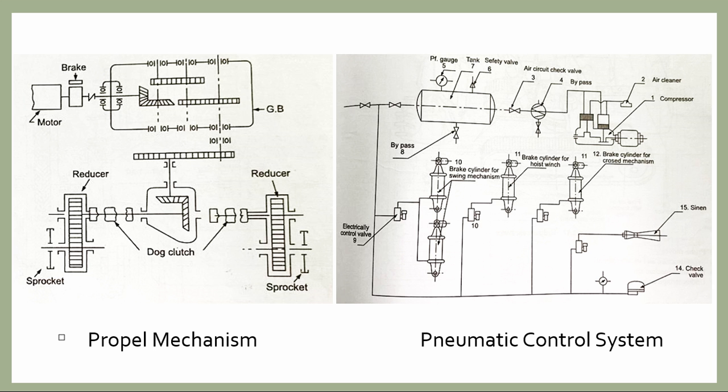Here the reducer is connected to the motor by the flexible coupling, and the reducer is designed in this way so that it can easily connect with the motor by the flexible coupling. So the bevel pinion receives the power from the motor through the coupling, and the bevel gear is in mesh with the pinion.